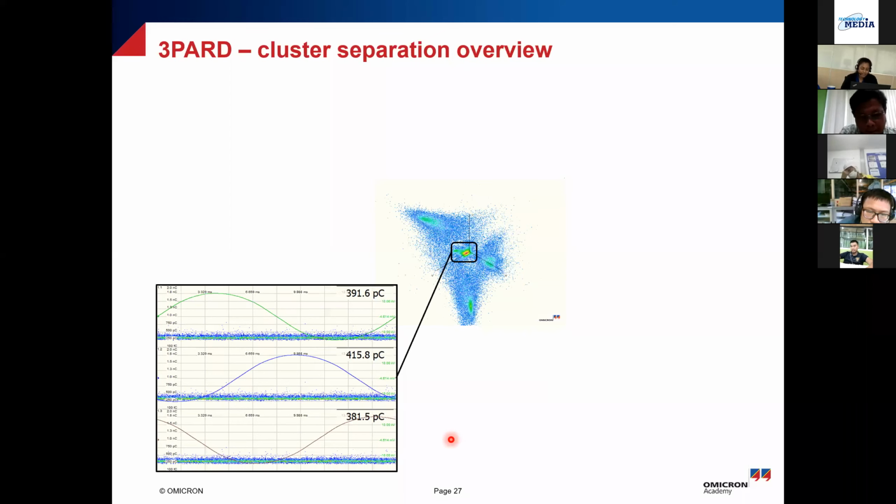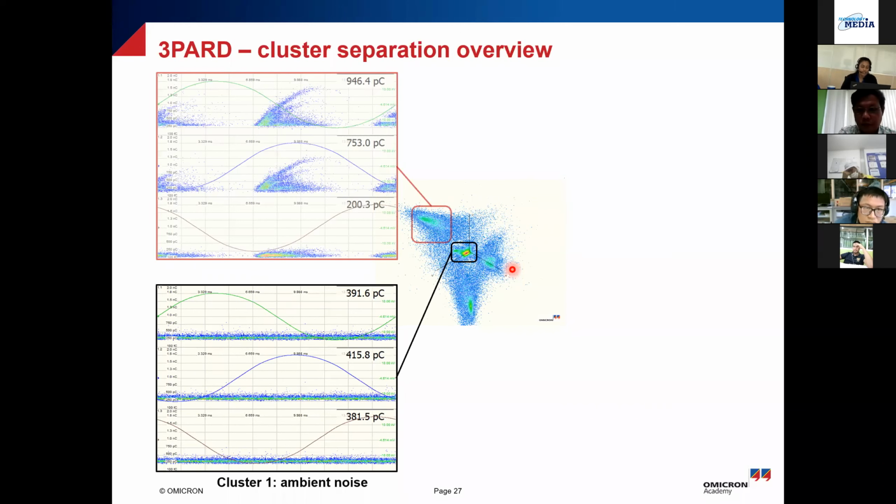is pretty powerful these days, right? So you can also get automatic pattern recognition. And here I can say, okay, this is not AI, this is just my calculation, but you will also see this in AI. So this one corresponds to ambient noise. Sorry, yeah, this one corresponds to delamination, and this is high risk. I mean, you can refer to the IEEE guide for this.